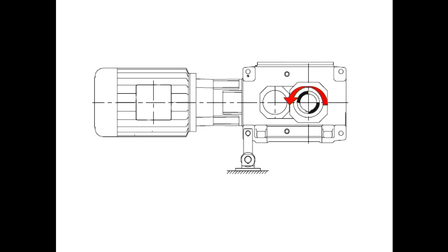So I saw this shaft and I thought, hey, there's no 45 degree bits on it. It's all flat. So I thought, this looks as though it's failed in bending. But anyway, then I thought, hey, fatigue.